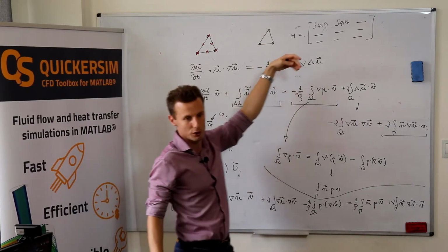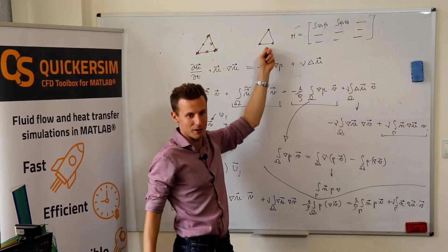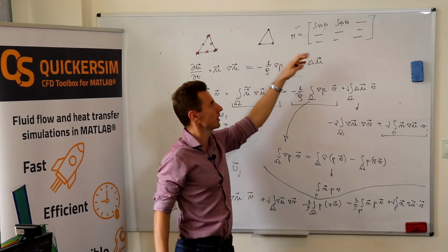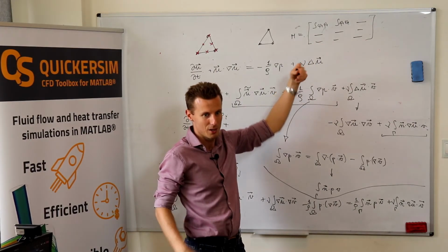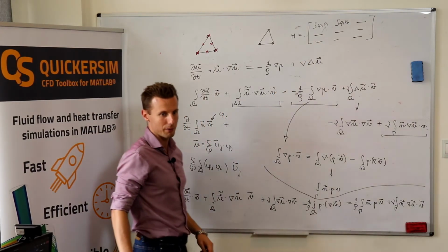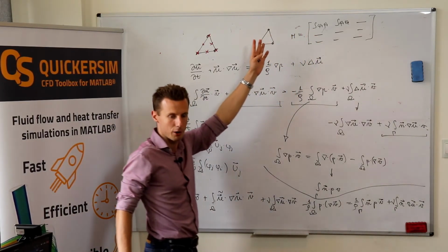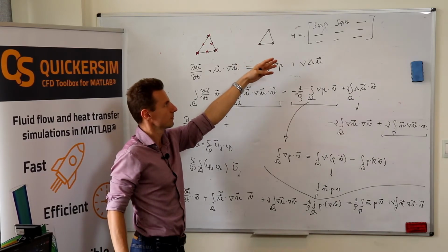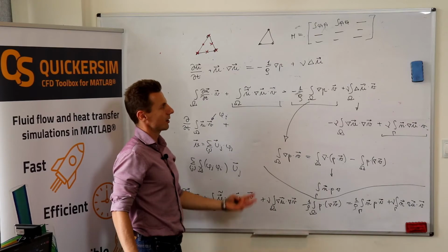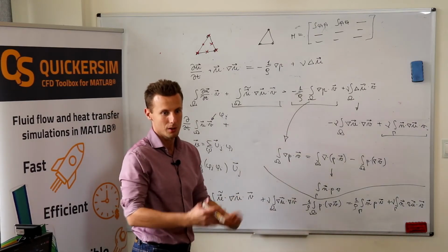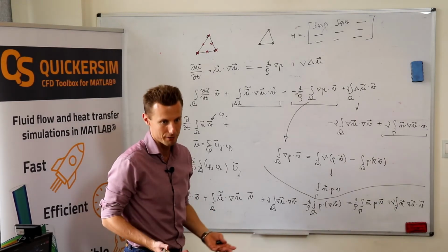So you cannot write it explicitly, because even on the local level, you need to solve a system of linear equations with such a matrix to calculate the nodal values. So if you assemble the global problem, you have no way to decouple the nodal values at the new time level from each other.